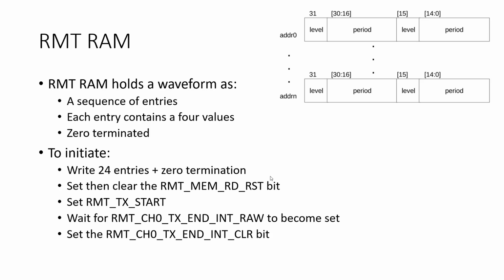So the way I did it was I programmed 1 LED at a time. Pretty much what you do is you dump 24 bits into this memory, and then you tell the thing to go. Then you put 24 more bits in the memory and you tell it to go. That way you'll get the first LED and then the second LED will be programmed, right? Do you guys make sense? So in other words, when you tell the RMT to go, it's only actually setting 1 LED at a time, right? Meaning you populate 24 entries.